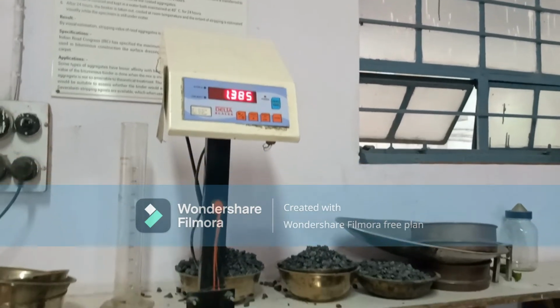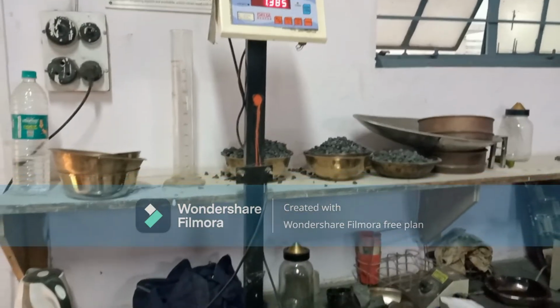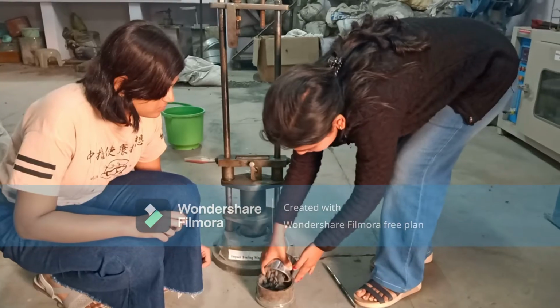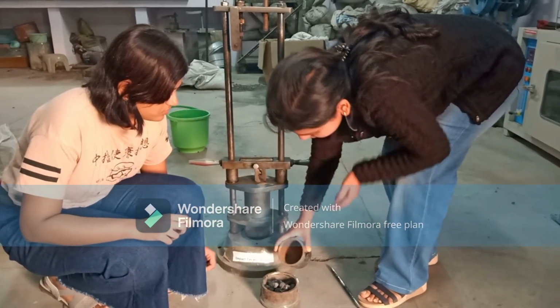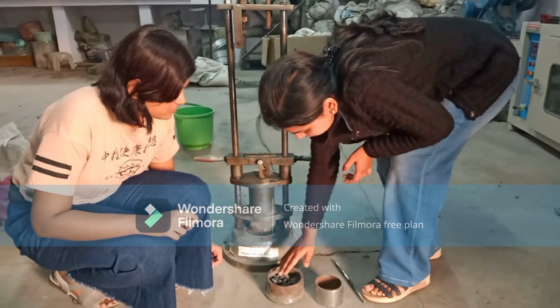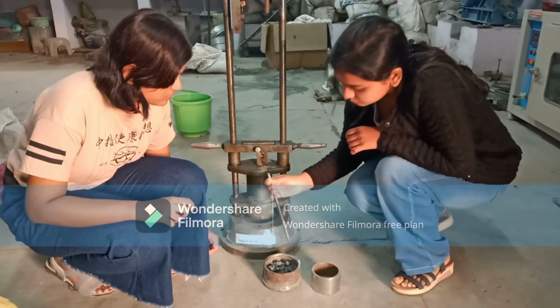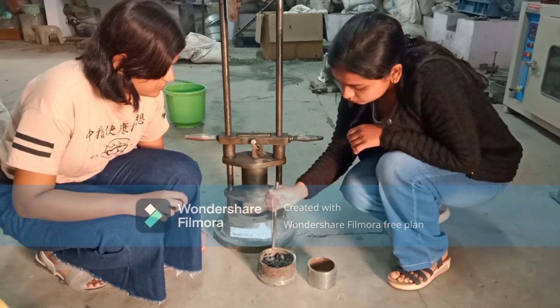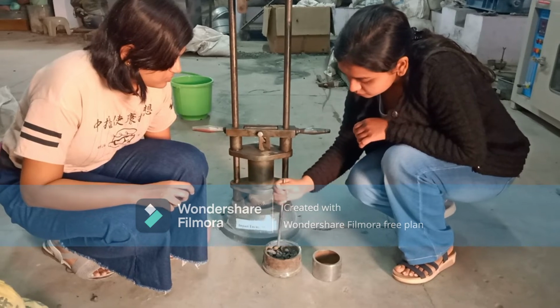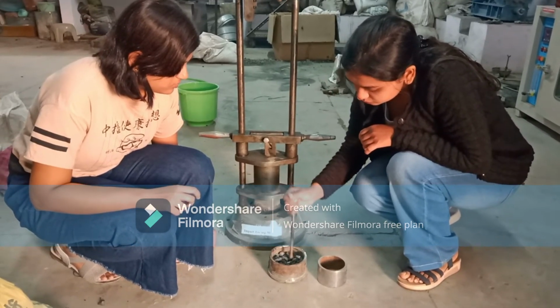We will now measure the weight of the cylindrical container along with the aggregate. Now we will put the aggregate from the cylindrical measure into the cup and we will tamp it 25 times.